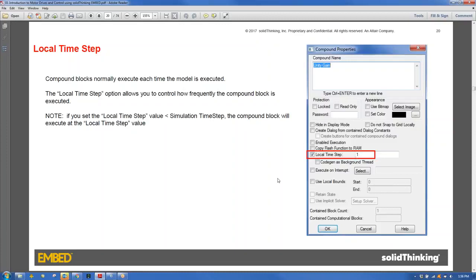In embedded systems, you're going to find this very helpful because we're going to have main control tasks that have to run very fast, and then we're going to have background tasks that don't have to run fast. They might just communicate information to or from the PC, and they can run slowly. So you're going to want to use this feature to identify background tasks and run those at a very large time step, and run the control tasks at a very small time step. And that's essentially what we'll use this for when we get to the motor control part of this course.